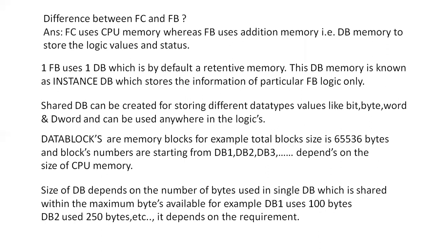Now we see the data block addressing format. For example, we are creating DB1. First, we have to give the data block number, DB1, meaning from which data block we are taking the address. If you are taking the address from DB2, first we have to mention DB2 here, DB2 dot, like that.